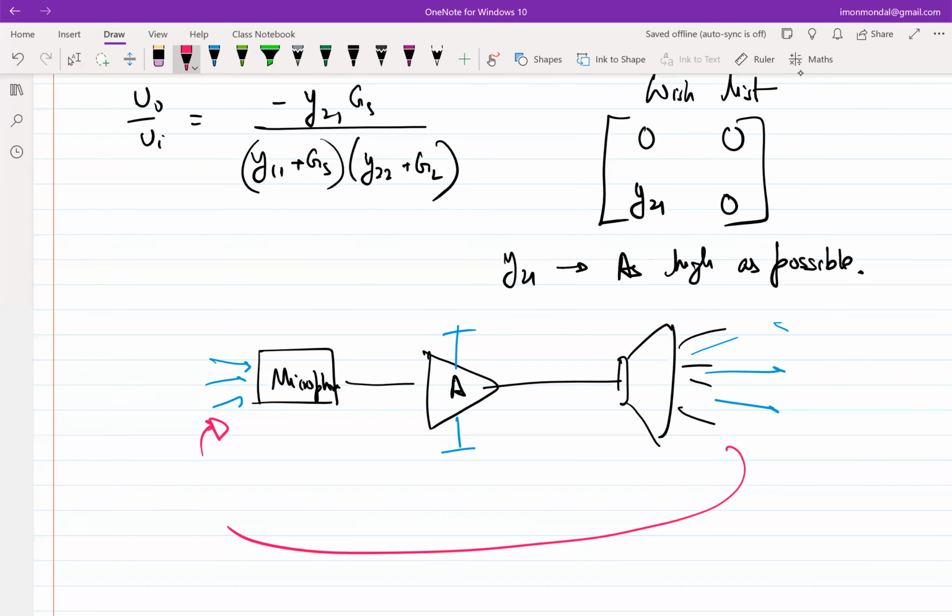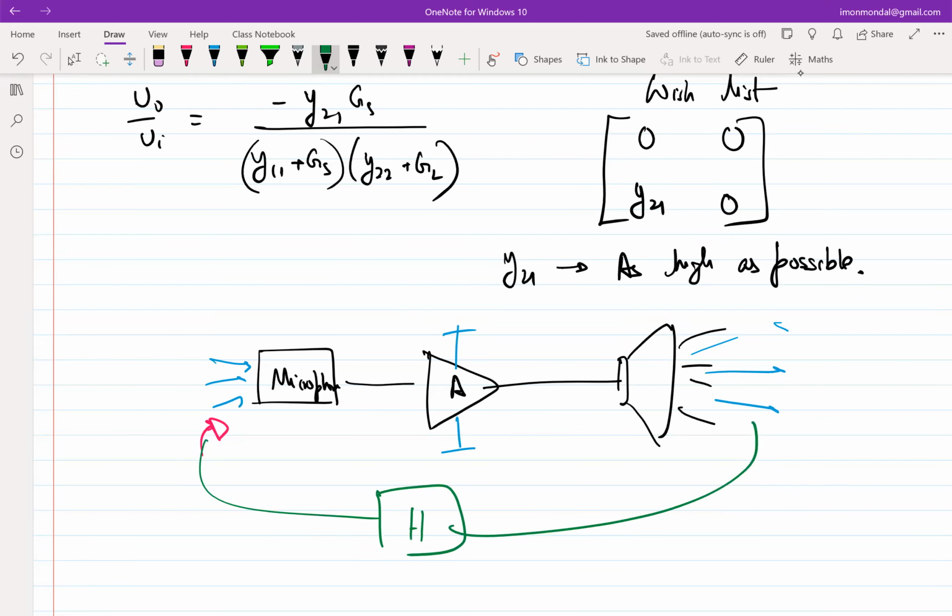Right. So this keeps on happening. So why does it happen? This is equivalent to saying that I am increasing this feedback factor, right? So you can assume that there is some sort of transfer function H kind of thing here. If the larger part of the signal is getting intercepted and going to the output, then it's possible that you hit that spot of GH is equal to -1 and things can start oscillating.